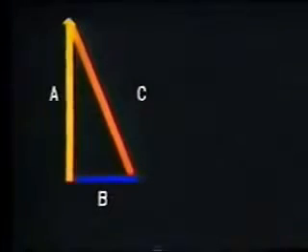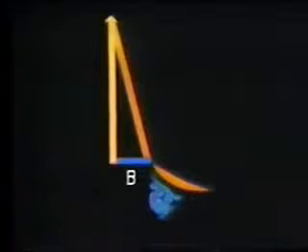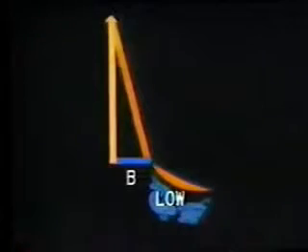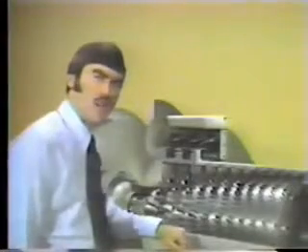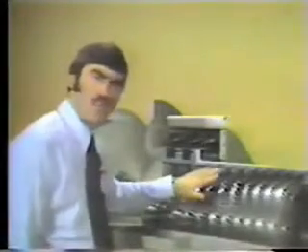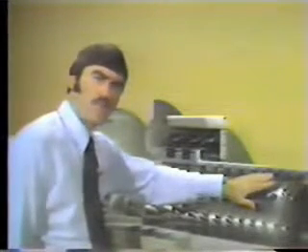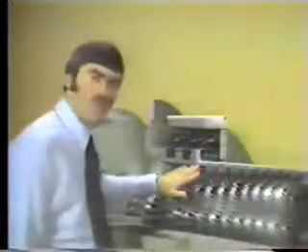Vector C meets the airfoil at an increased angle because air velocity has been reduced to half. If the rear stages continue to choke and the air velocity drops very low, it's easy to see what happens. Though the blades continue to rotate at the same speed, the airflow almost stops. Here, vector B represents very low air velocity. The relative angle of air meeting the foil is so great that turbulence develops. And that important low-pressure area over the foil is destroyed.